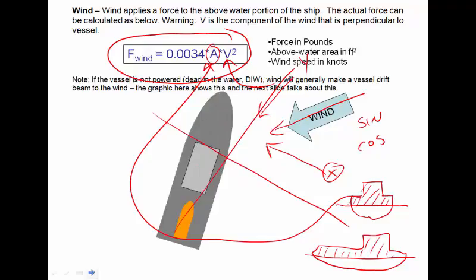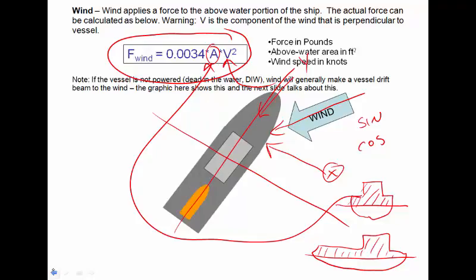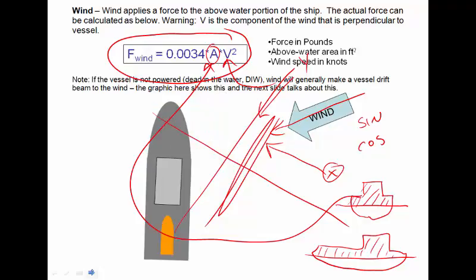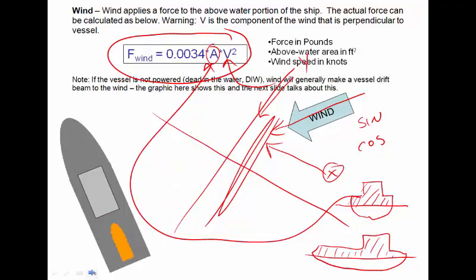As you can see, this vessel continues to get pushed, and because, if we go back one slide, this vessel has a large amount of sail area on the beam over here, it's going to continue to get pushed both down and to port. And you can see that happening in this graphic here. It gets down into port until it gets about to beam to.